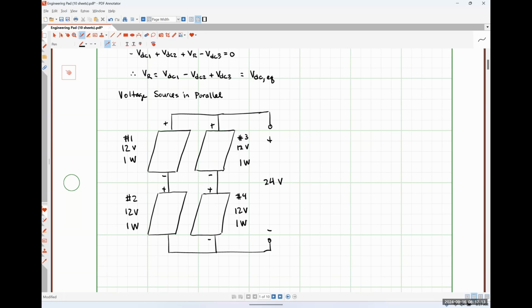So as part of my job at Sabre Industries, I design these battery energy storage systems where we might have 22 racks full of batteries providing somewhere in the ballpark of 1500 volts, but we wire them all in parallel so that we can get tens of thousands of amps out of these batteries. 1500 volts is what we would consider in the industry a medium voltage, but we're able to produce megawatts of power out of these systems to help large municipalities like the city of Los Angeles ride through blackouts.